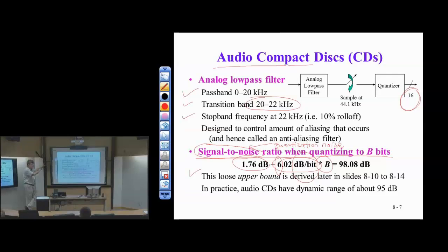This is one channel of quantization. That's what PAM is. PAM in the end is one channel. It's one dimension. 6 dB per bit works for PAM just as well. So it's the best we could do. If we were to do PAM over a channel with 50 dB with this offset of 2 dB, the best we could do is 8 bits. Now in practice, we'll probably back that off and do 7.